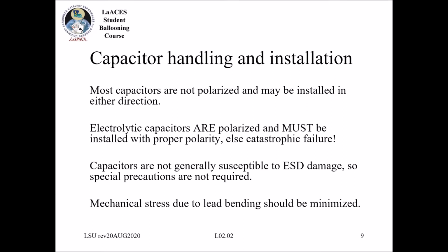Okay, so again, we're talking about the polarization. I'm just going to re-emphasize it. Install it in the right direction. If it is polarized, it will definitely cause damage to your entire circuit, and it might release the sacred smoke that we mentioned earlier. It's not a good thing.